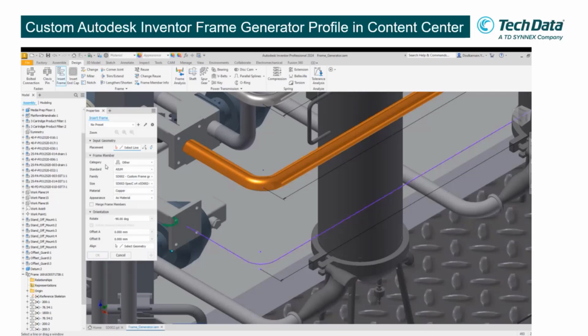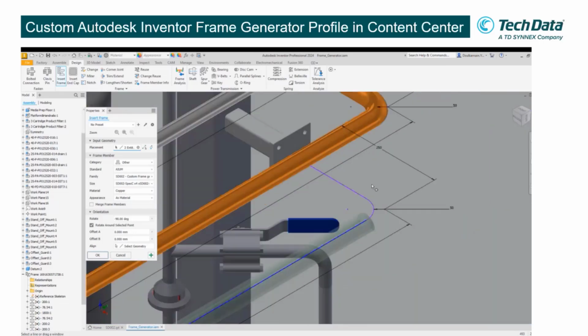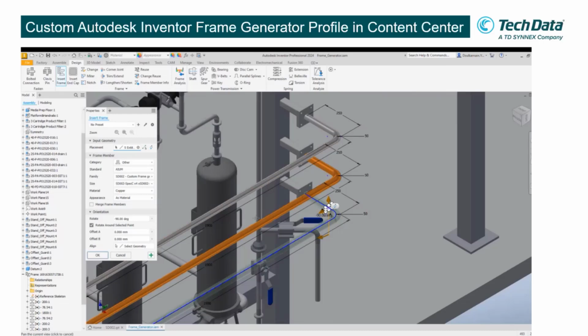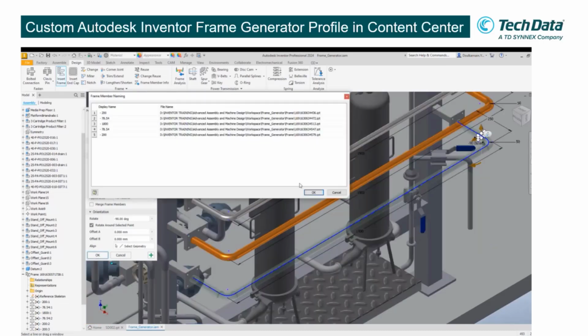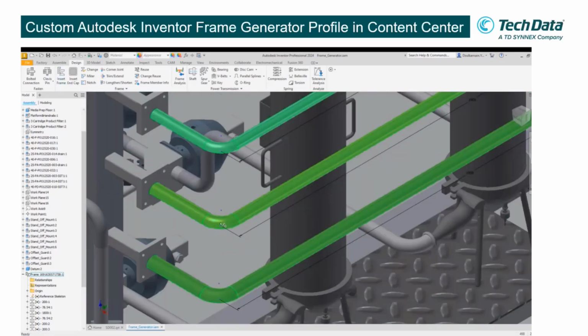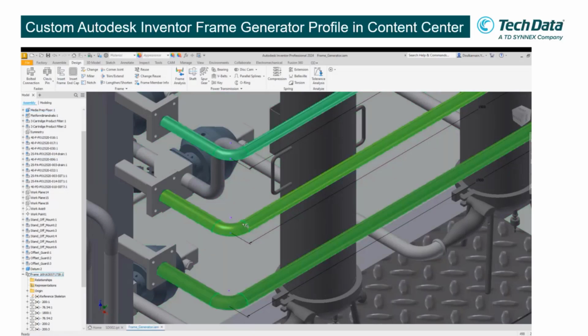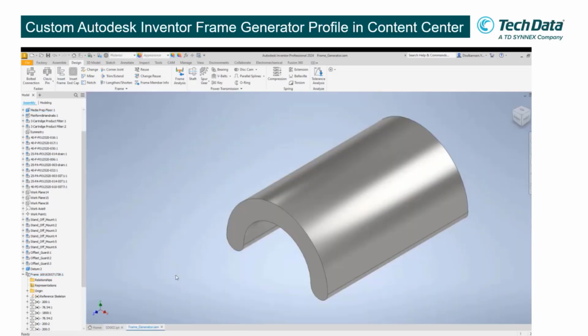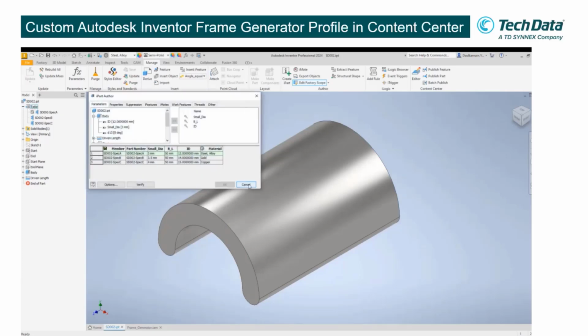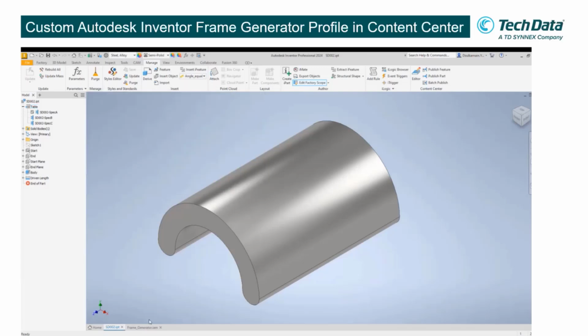And then maybe I change to spec number 3. Now for the bottom one, change to the other specs. See if everything is correct. It will update. So you can see three different colors with three different specs. Let me go here and see my iPart table. You see we have steel, alloy, gold, and copper: spec A, spec B, and spec C.